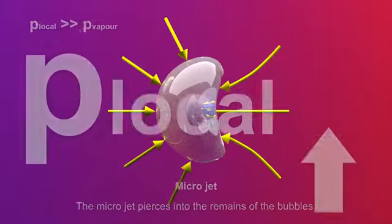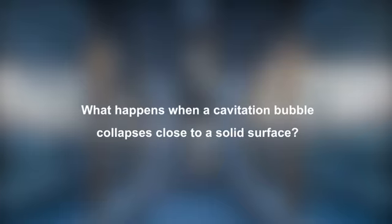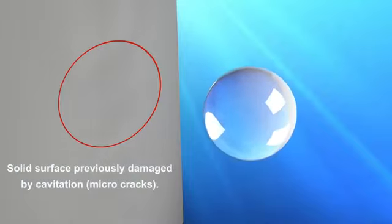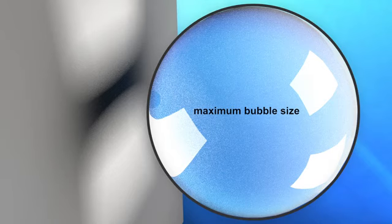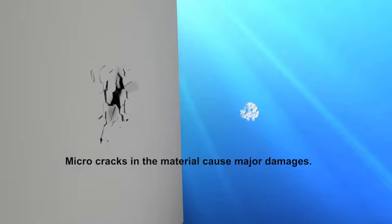The bubble is now collapsing. The bubble becomes a torus and disintegrates further. The microjet continues to flow in the liquid and can hit a wall. Through its concentrated impact, even high-strength material can be damaged. The implosion releases energy in a very short time concentrated in a very small spot. If the microjet hits a surface, it damages the material by a localized short-term overstraining. The material starts to evolve microcracks, and later material can break off.